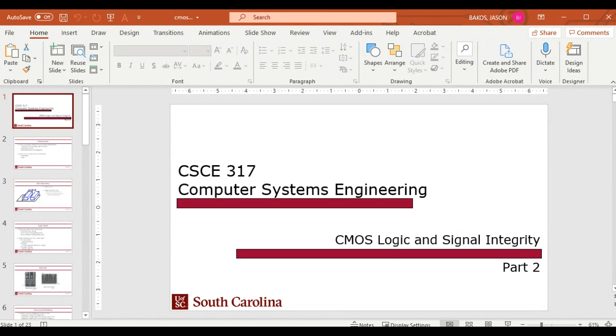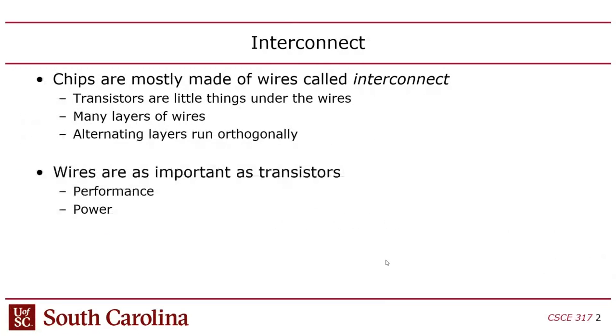Okay, all right, here we go. So the next lecture is about interconnect. Previously we looked at delay, but we looked at gate delay. We didn't consider interconnect delay. Interconnect is the wires that connect the gates. Those have a significant impact on performance and power. So basically what I showed before was a little misleading in the sense that I didn't consider the wire delay,